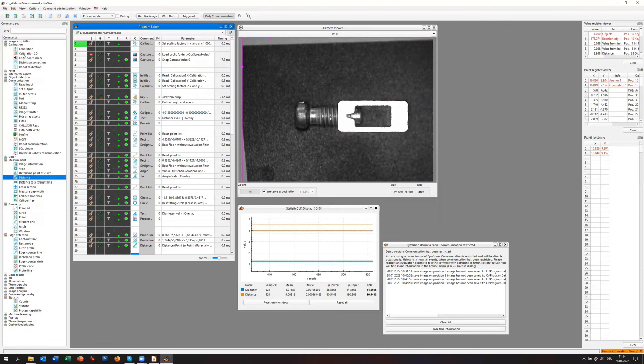And the real advantage of the chessboard and point calibration is that you also do correction of the lens distortion, which makes it much easier. Then you could also correct not so good lenses and measure in the complete field of view with the accuracy of the correction factor.